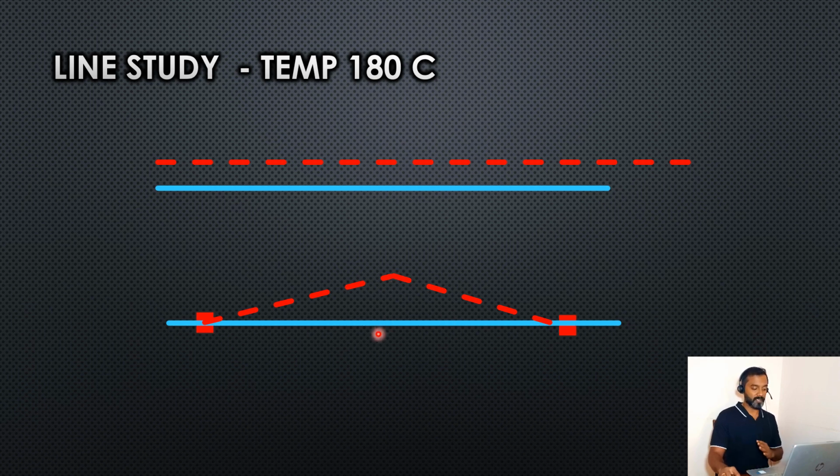So this is one of the key points. If you arrest two locations of a straight line, the line will buckle, so that it will cause tremendous damage to the piping material actually. So this will try to expand, and over a period of time the deformation will be permanent, and there will be fatigue and there will be a rupture of the material as well.